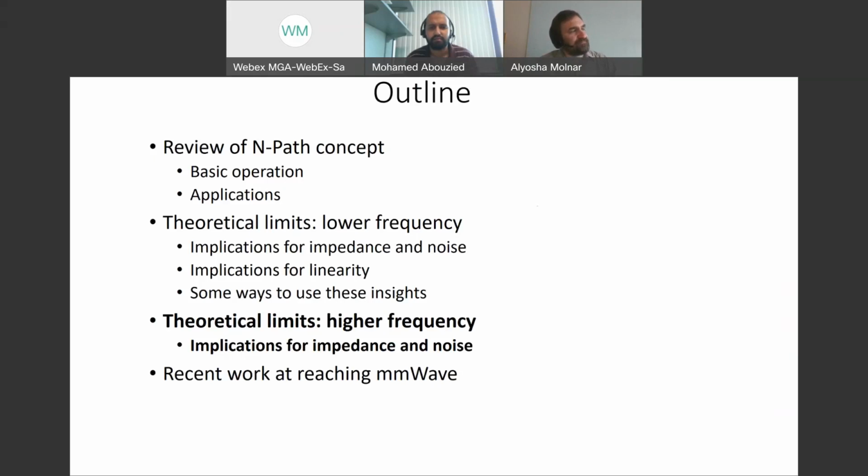The downside of that is that you have to have a significantly better baseband amplifier, because it has to actually maintain that low impedance on the input the whole time. And actually, the place that usually becomes a real problem isn't in band, because in band you just have a lot of gain, you're great. And it's not way out of band, because way out of band you have a capacitor shunting you, but sort of middle out of band, sort of in the band edge.